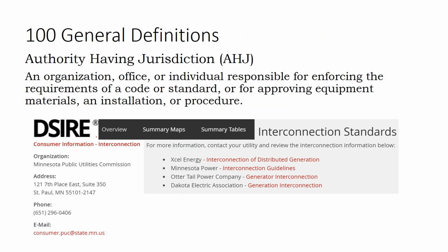Yeah, there are custom calculations designed for things like an electric range stove, where the circuit has to be sized as if the stove had all 4 burners or 6 burners on 10 out of 10 hot rating plus the oven on. But that doesn't mean that, in terms of sizing the power supplied into the building, you have to assume that all the devices in the building are on at once.